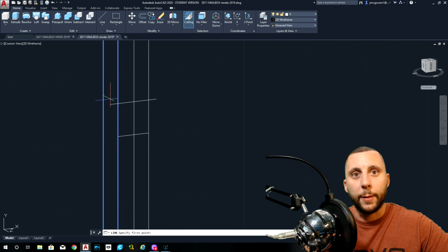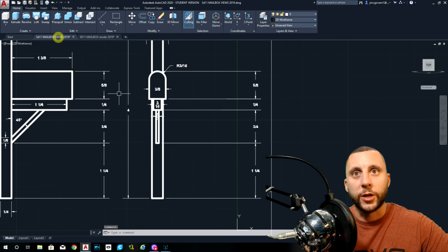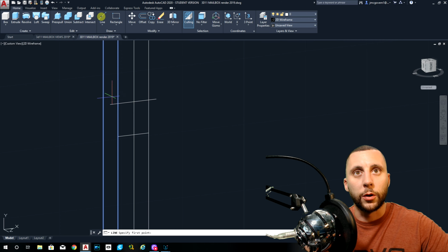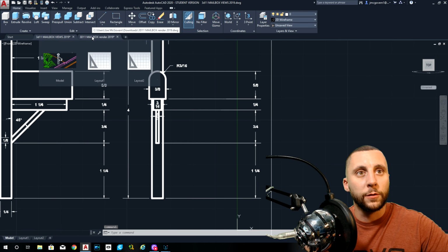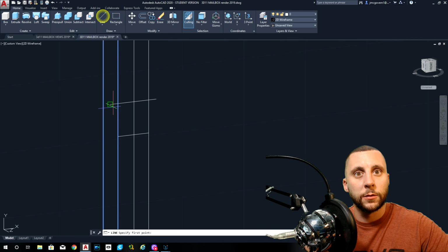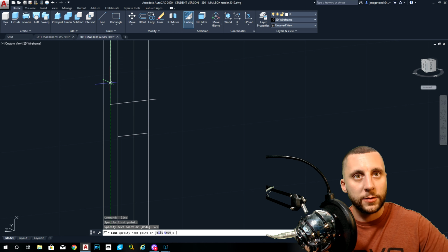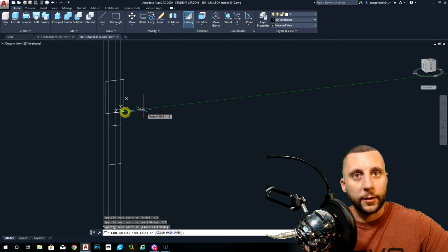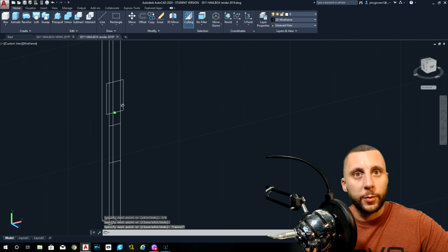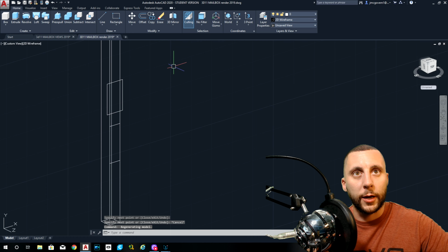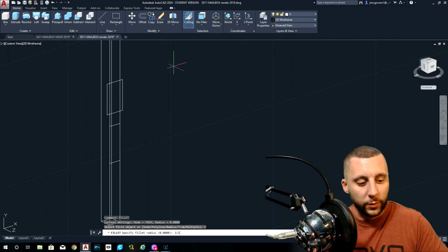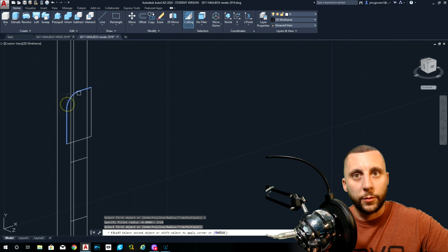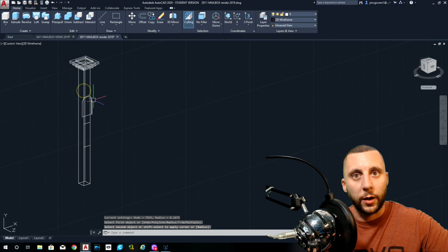Okay. And from that point now we can draw up, although I've got to check how far. It looks like the entire mailbox is 5/8 inch tall, and then it's got a radius 3/16 fillet on the top. So we're going to go, what did I say? 5/8, radius 3/16. So you're going to go up from this point 5/8, across 3/8, and then come back down. This might be a little confusing, so maybe I'll orbit a little bit more. We're going to do a fillet radius 3/16, and that's going to go from there to there and from there to there. Alright, so you've got that.